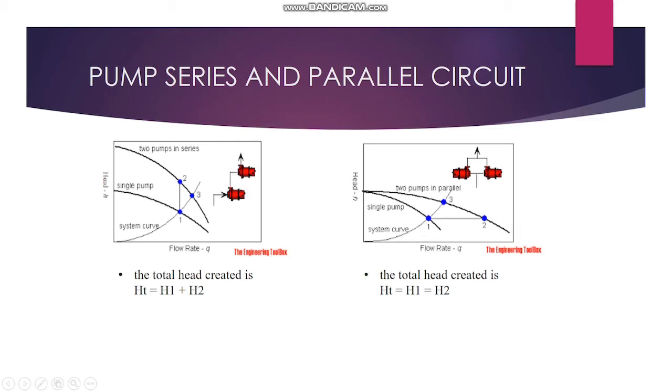Okay, for the parallel, when the pumps are connected in parallel, the head is equal. This is H total equal to H1, equal to H2, and the flow rate will be increased.